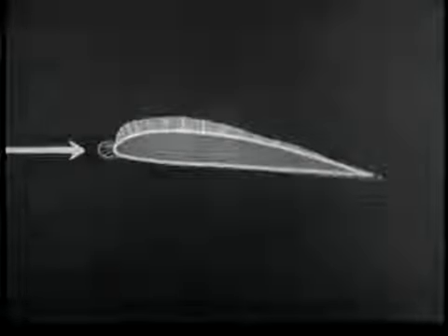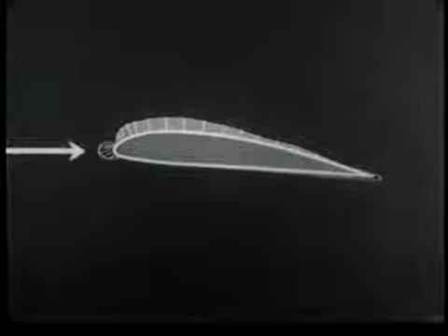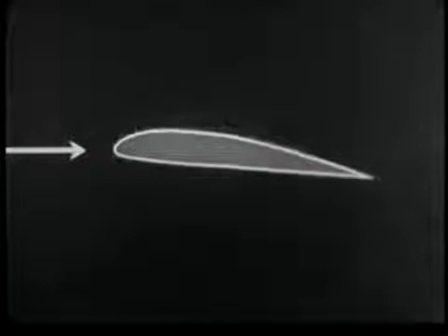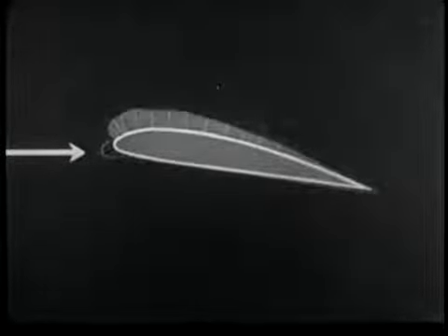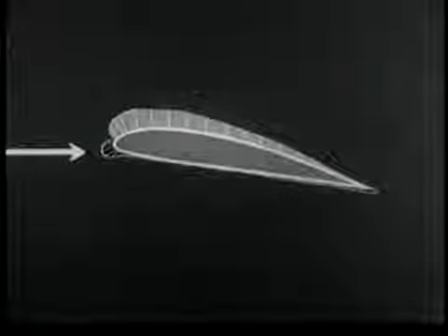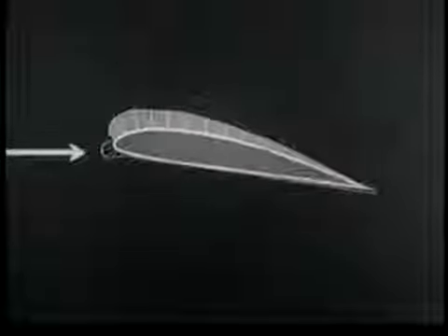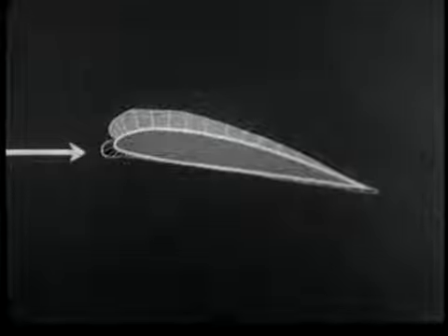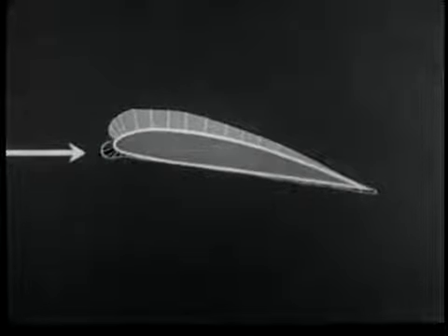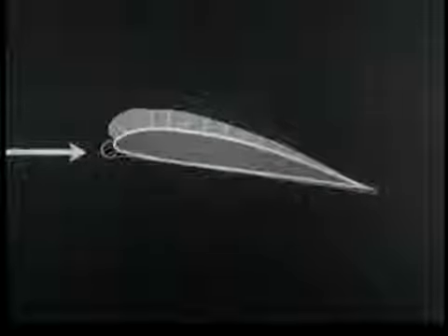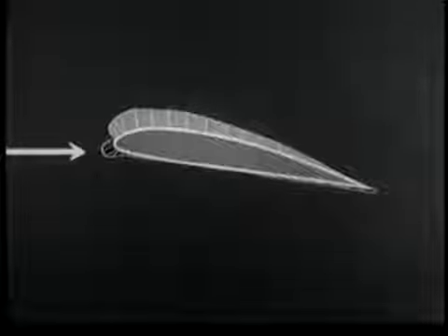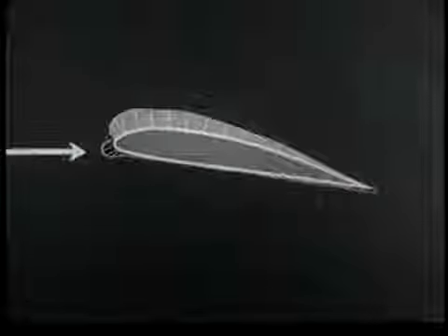This diagram indicates that the wing has begun to exert a considerable lift. Increasing the angle of attack still further alters pressure distribution very little, although there is a marked change in values, particularly along the upper surface, where negative pressures are now exerting a powerful lift force.